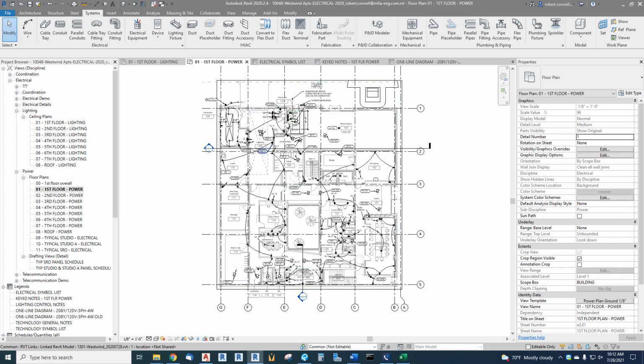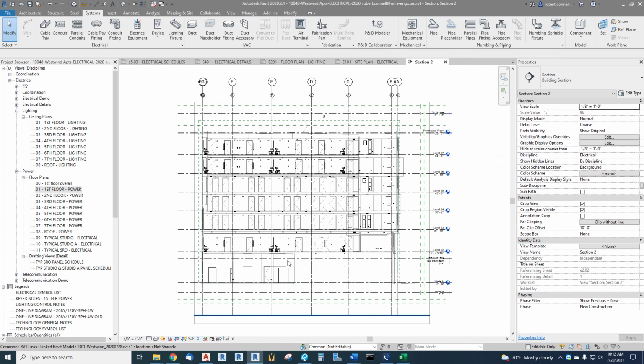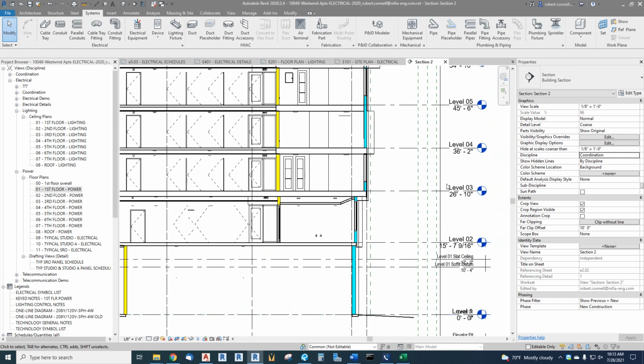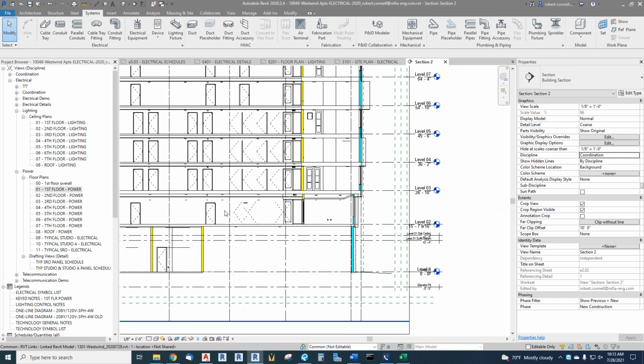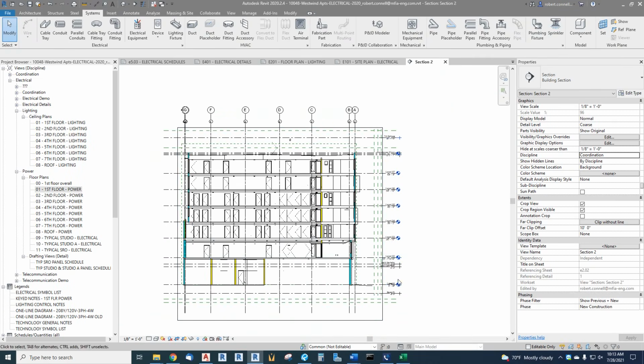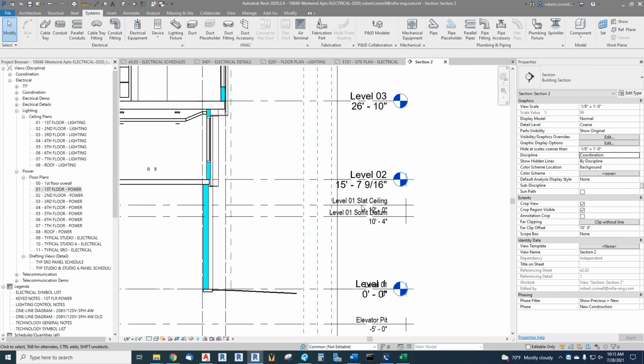Let's do another section. Here's a section that cuts through the entire building. There. See, now you can see how handy this is for getting an idea spatially of the building. Sometimes you'll end up with very complicated levels, multi-level stair-stepped buildings, partial basements, raised stage floors. You can see here the architect has a number of other levels that we have not copied. We don't need them for our purposes, but if you do, you can copy them over.